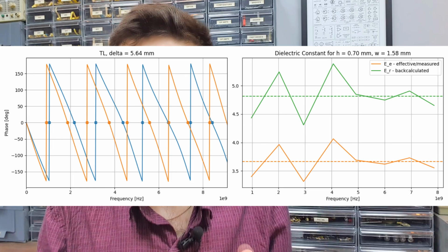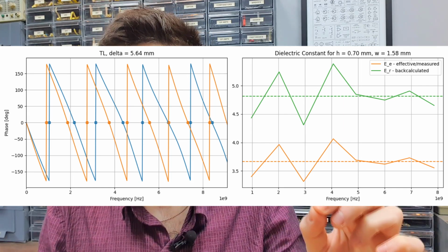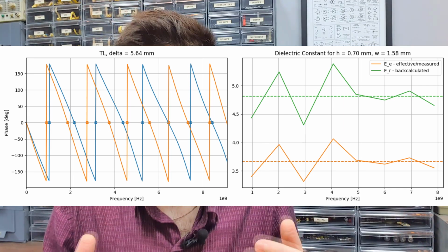Phase profile is directly related to the electrical length of the microstrip. And having the two measurements, we can create a system of equations that computes the electrical length, thus the effective permittivity, using the two phase profiles and the length difference, not relying on the absolute length of the microstrips, so canceling or removing the effects of the SMAs.